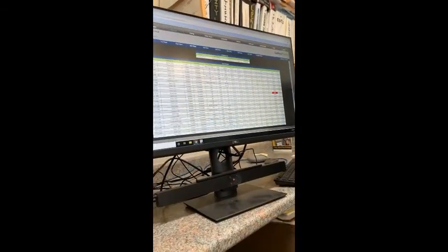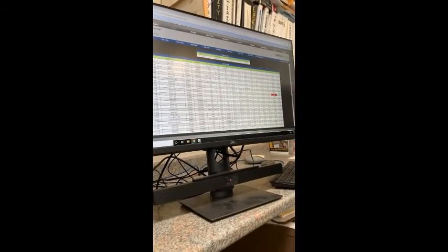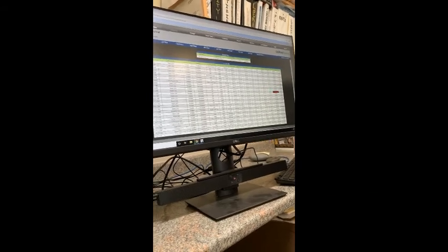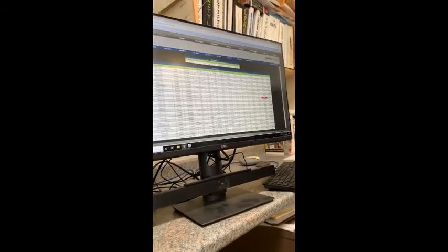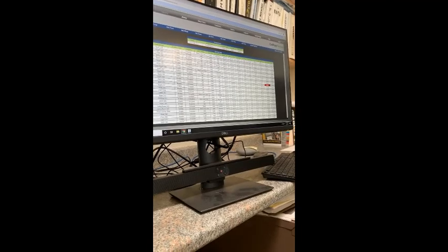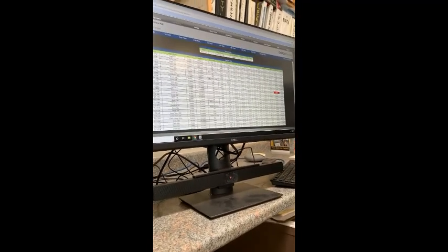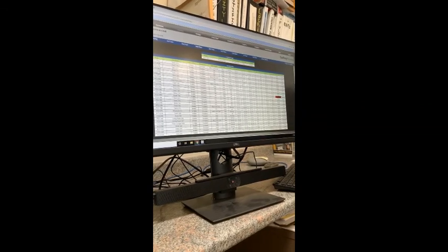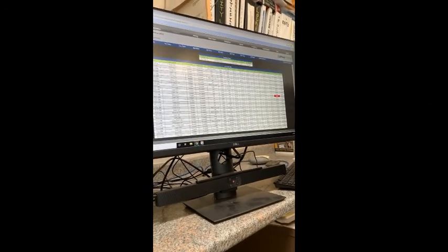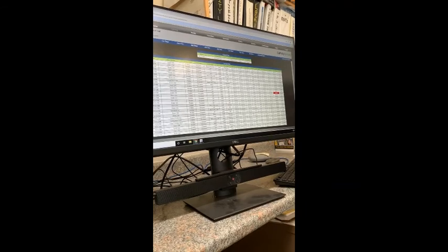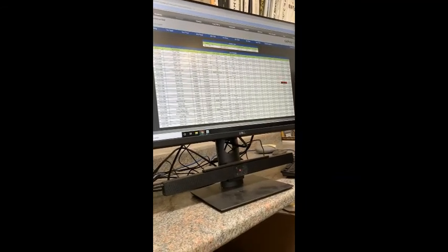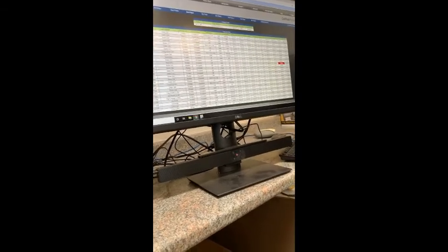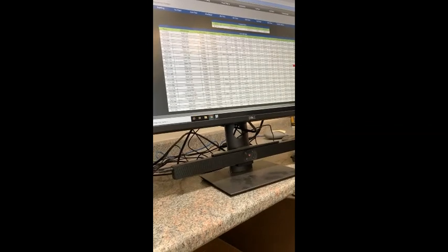If it's telling us open and the window's closed, and we shift it to closed on here, if the sensor is telling it open still, is the open going to come back through? So as far as the code and override operation, once it's overridden, it would work however you override it, and it would think that's the state it's in. Then once it was autoed out, it would release back to whatever status it's actually reading.